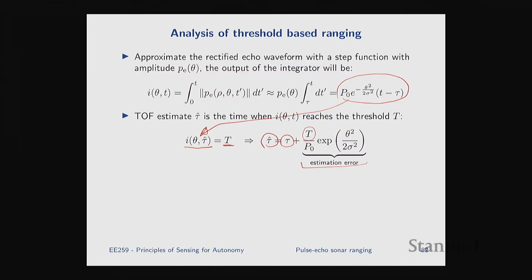Well, because there's always noise. So the output of your integrator is always greater than 0, because even when you haven't received any echo, there's noise and a little bit of interference and other effects. The picture we're looking at here looks nice and ideal. But you can never have a 0 threshold, because if you set your threshold too low, any bit of noise spike or something randomly generated in the system causes that output to cross it. So you're going to get a ton of false positives if you set your detection threshold to 0. So bad idea. We don't want to mess with T too much. You usually even set it a bit conservatively to limit your false positives.